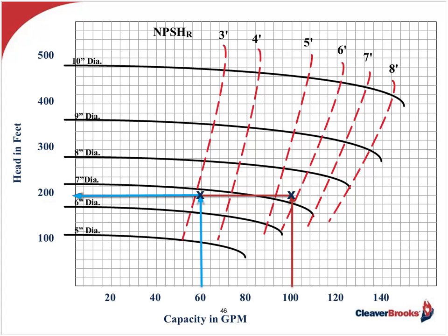Now here's another example. In this case, we'll assume the boiler was changed out because of an increase in load, thereby increasing the boiler capacity. But the DA stayed the same, except the pumps were changed out to add more capacity, but no other changes were made to account for the possible cavitation of these pumps, such as increasing the stand height.